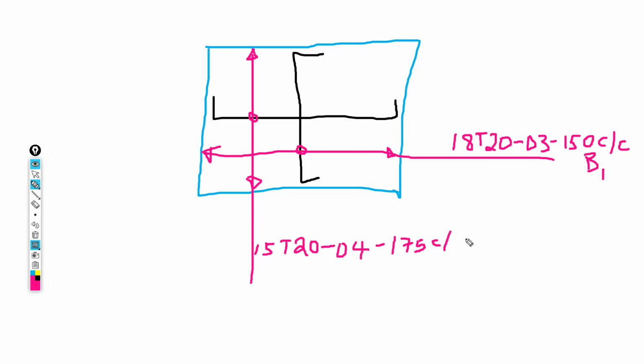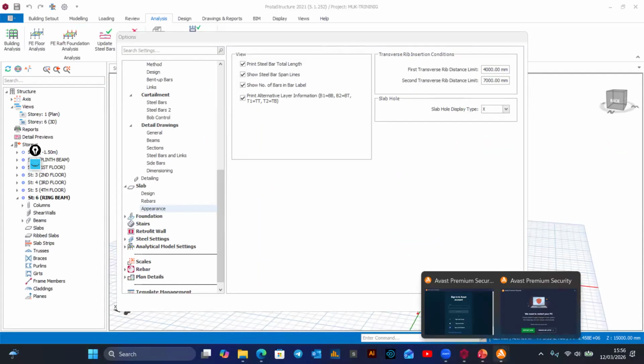Center to center. So I need to know, is this bottom reinforcement or top reinforcement? It is still bottom reinforcement. Okay, it's still bottom reinforcement. I have at the bottom bars running like this, and also a mat of bars running like this. So yes,